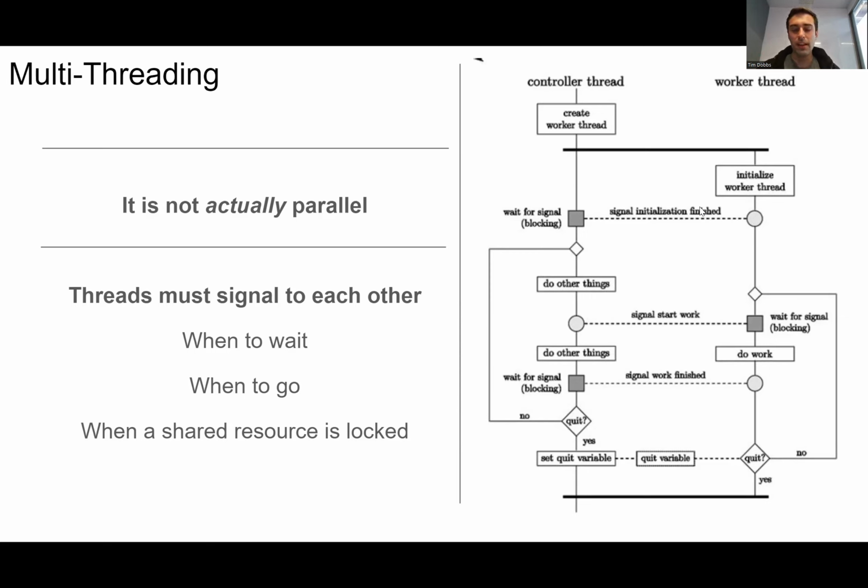There's some silicon inside my microcontroller that is keeping track of the number 30. When is that available? If I'm writing to it with my measurement and then I start to read it halfway through, because remember, these calculations can be interrupted, there's just going to be garbage inside of that memory address. So when I'm writing to memory, I have to say, hey, I'm using this memory address right now. And then my network reporting thread can say, oh, now it's become unlocked, I can now read it.